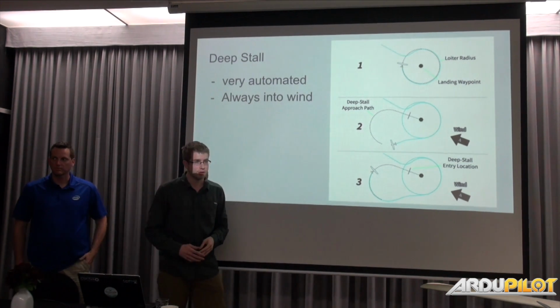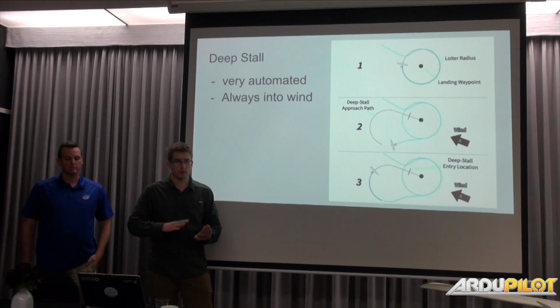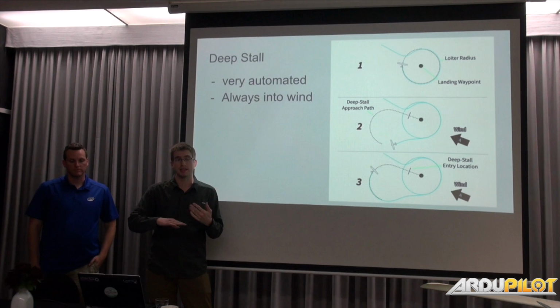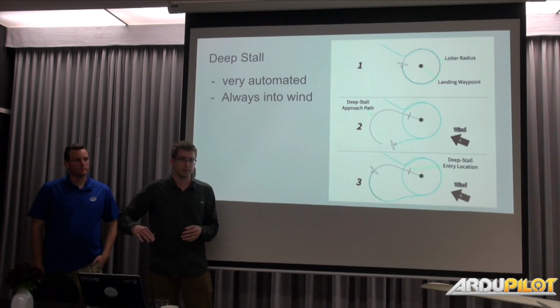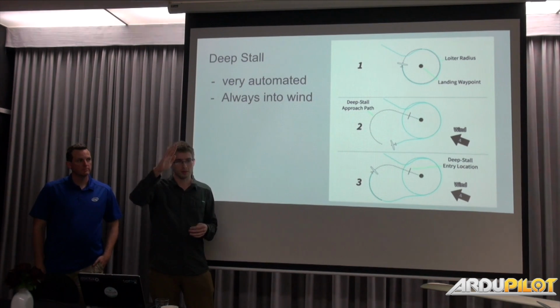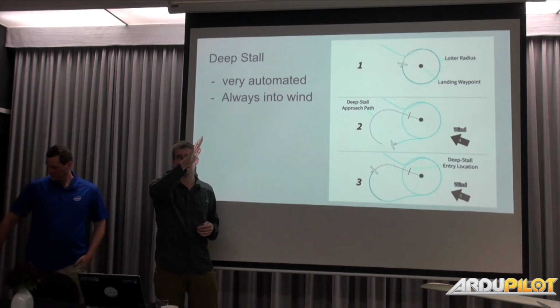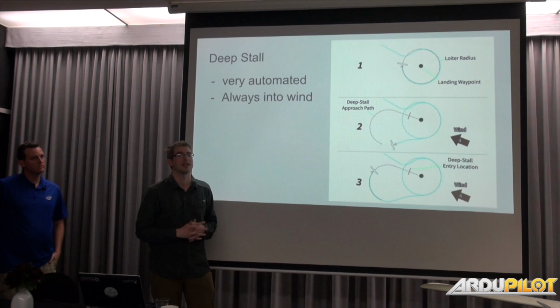But when the aircraft hits that, it'll flare, it'll enter the stall, and we'll do a couple-stage transition where, depending on the indicated airspeed, we'll reduce or change the amount of control authority we have. Because as you do this high alpha and enter a 45-degree angle here, you don't want to be putting in a lot of rudder, because you end up tipping over and can enter a spin.